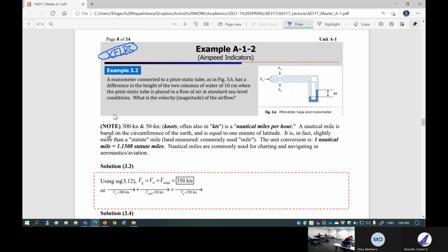So you can design your shape to begin with, the cross-sectional shape. Okay, this is my choice of cross-section. How's that? You can even design it and name it. There are a tremendous number of wing cross-sections, and there are so many names. Some of the names are of someone who actually created them. Well, I'll make this name Hayashibara cross-section. You can do that. You can design your own cross-section to begin with. And then based off of it, you're going to analyze the aerodynamic properties of the cross-section, 2D aerodynamics.